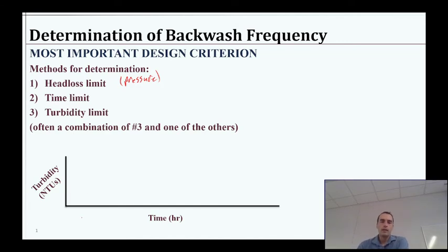So if we have a system here and we start with a freshly cleaned or freshly installed filter, we can say this is clean to begin with. Then the first little bit of time is going to be that rinse stage, so we'll rinse there. Then we're doing production for some extended amount of time, hopefully. So we'll have production or filtration time.